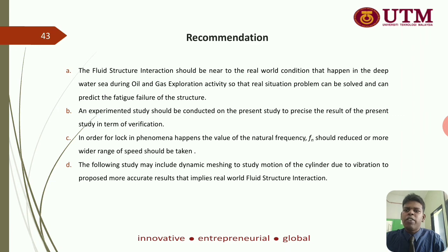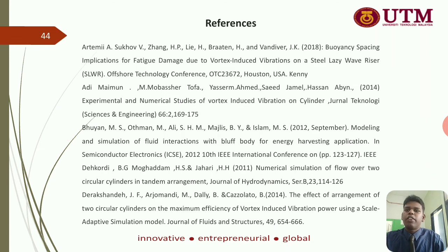In order for the lock-in phenomenon to happen, the value of the natural frequency should be reduced or a wider range of speeds should be taken. The following study may include dynamic meshing to study the motion of the cylinder due to vibration, to propose more accurate results that imply real-world fluid structure interaction. Next, we see the references used for the simulation study.